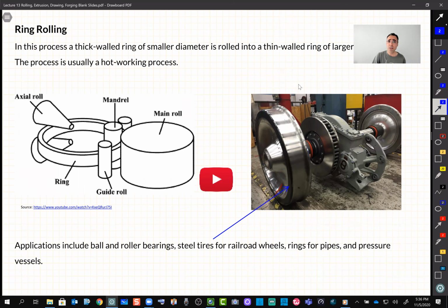And also we want a lot of them, so we don't want the process to be super expensive. We can make them by machining, let's say with the CNC process. However, the process then requires a lot of hardening to get the surface hardening, and maybe we don't get the desired strength that we wish to have.